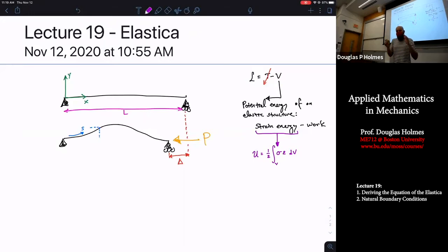And what I want to emphasize is that there is a difference between small strain and small slopes. And both of those are approximations that can help us at various times. Here, really, there's not much deformation in this elastic body until you get to about maybe here, where you start to feel the resistance in that bent bar. But doing this really takes very little energy. It's almost like a soft mode, like I could barely apply any load to it and I get this large deformation. So in this case, we're not really straining the material.